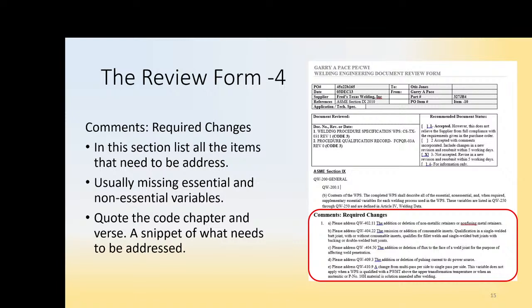You shall do this. First time I reviewed a WPS, I went through it with a red pen and marked up all kinds of stuff. And my boss at the time, real good guy, Dave Shaver, he's like, Pace, whoa, pump the brakes, dude. They're going to hit us for change orders. And I was like, this is a garbage WPS. He's like, read the code. Check only essential and non-essential variables. That's the only thing we can get them to fix. They need to address all essential and non-essential variables.